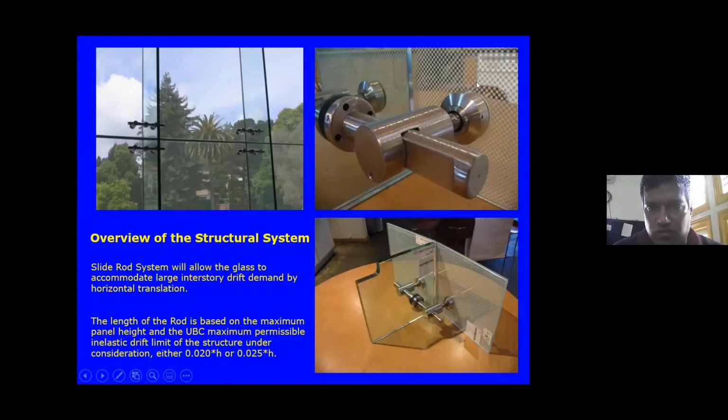These two bolts, and there is this rod. If you see this rod, it is typically not so extended compared to all the other structures. In this case, it was extended, and it was of course stainless steel, and it had this rubber bushing on it so that it could easily slide in and out in an earthquake. So this is how a second system was developed to accommodate the earthquake.